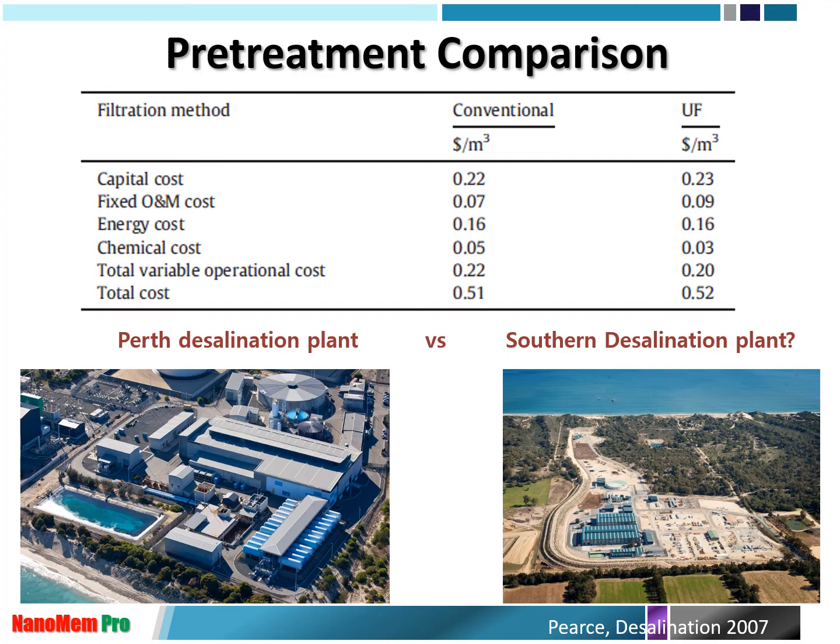So depending on your water quality, they will produce a different quality of pretreatment permeate, which is the RO feed water. So it's not consistent, therefore their RO performance is more fluctuating compared to the Southern desalination plant. So depending on your water quality, you can select your pretreatment process.